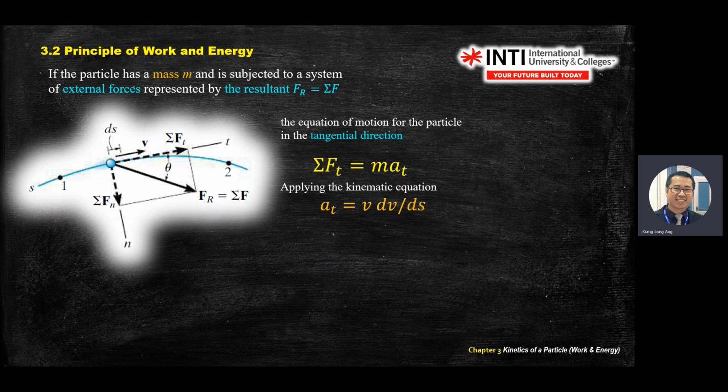And you need to recall one equation that you derived when you freeze the time for velocity and acceleration. V equal to ds dt, a equal to dv dt, you freeze the time. You combine these two equations, you get a ds equal to v dv.